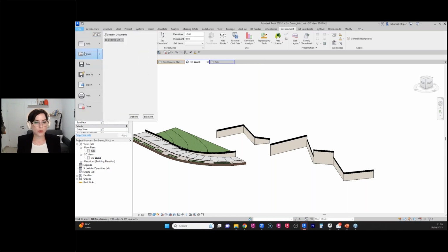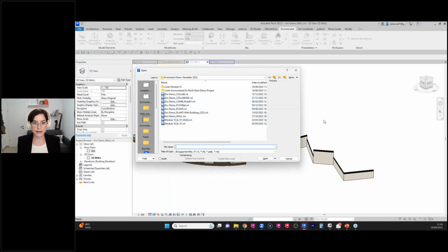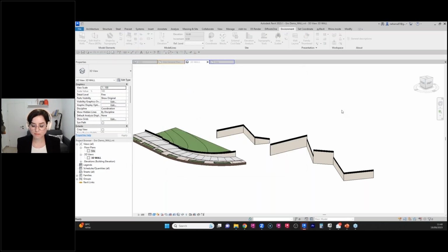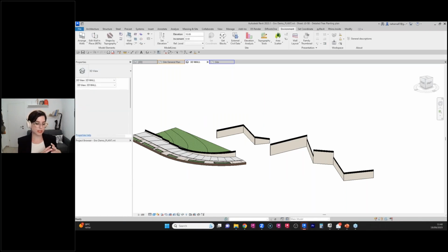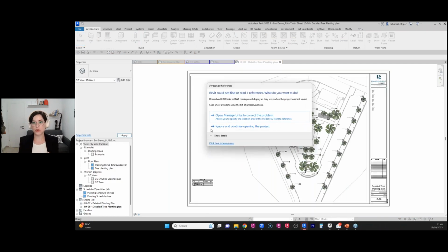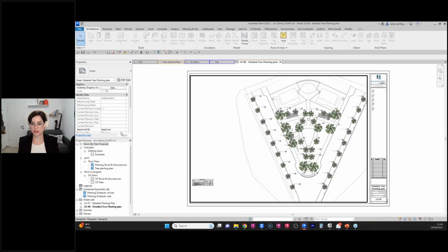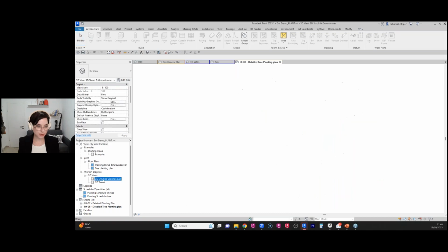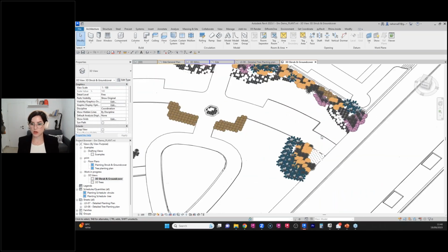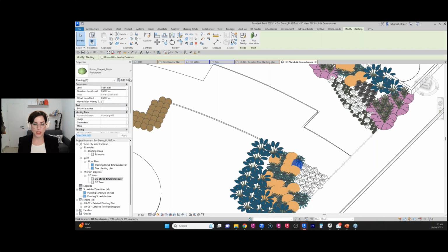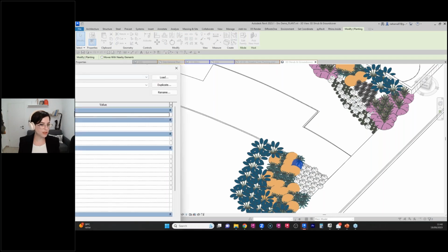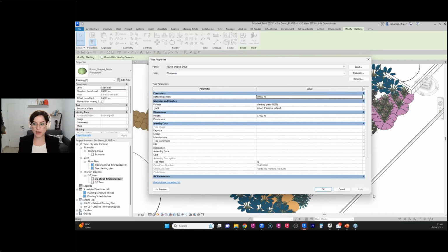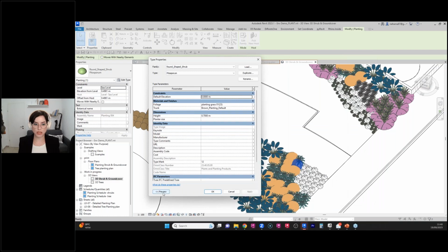Next, what I want to show you is some of the planting tools that we provide. So the way Revit works is similar to AutoCAD blocks, you have Revit families. Let's take a look at this 3D view. So each family in Revit can be duplicated into many different types, and every type can contain the planting information that you want.